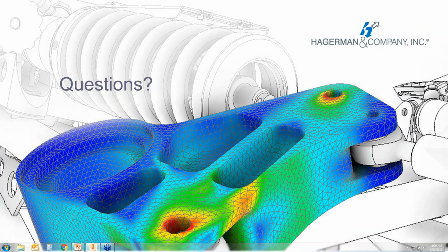One thing I've always addressed with anyone looking at nonlinear materials is just about every material on the planet is nonlinear beyond a point, including steel. But any rubberized materials, polymers, plastics, all of those are going to be nonlinear, and any results you try to do in Inventor are going to be inaccurate at best because of the nonlinear behavior.